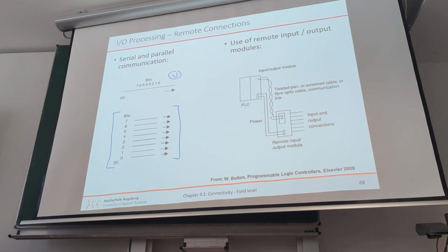So we use the high level signal and the opposite, the low level signal at the same time. And if you twist the cables and bring them from your source to your sink, then if there's any disturbance on the cable, it will usually affect both of the cables, and then you don't have a shift if you subtract the 2 signals from each other, because they are still affected in the same way.